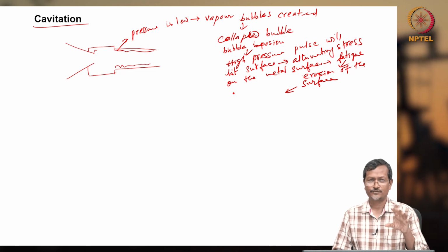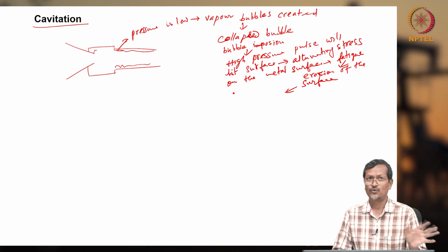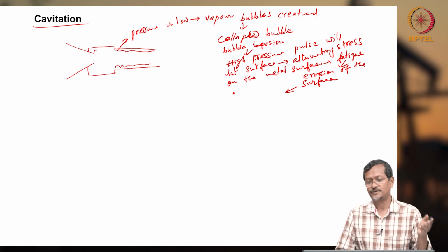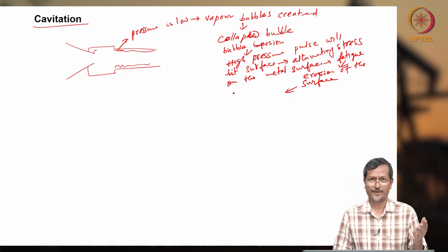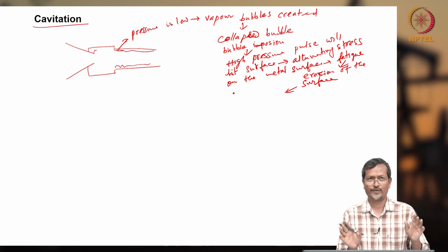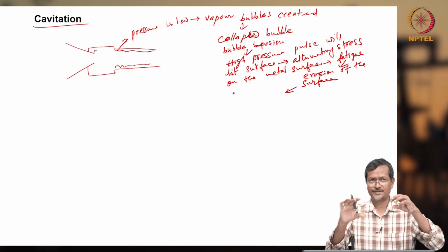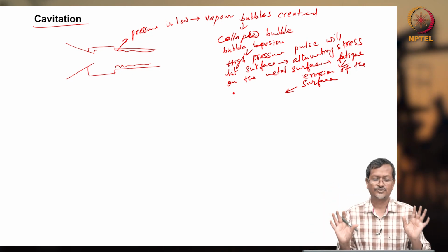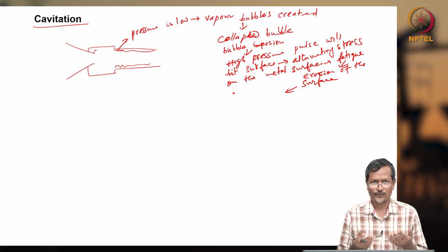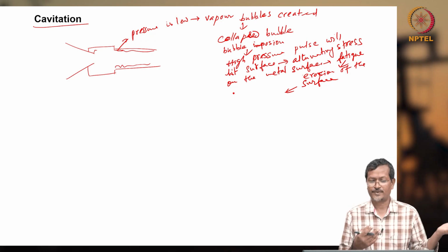The jet pump is the one system inside the wellbore where there is no moving part. But any sucker rod pump, PCP or ESP has lots of moving parts. When moving parts are there, life will be lower. But in this case, there is no moving part. One nozzle, mixing chamber, diffuser, done. Because of this, the failure rate will be very low, lower than any other artificial lifting system.